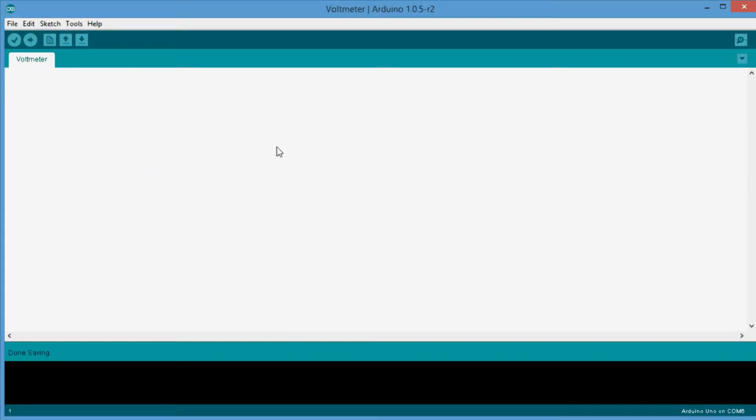So I'm going to get 4 bytes here, or 4 storage locations for each digit. We know that each digit only goes from the range of 0 to 9. And so we don't need anything very big to store that in. The smallest storage that the microcontroller can do is a byte, and that's 8 bits. That means it can store a range of numbers between 0 and 255. So these display digit holders are going to be a byte. That's all we need.